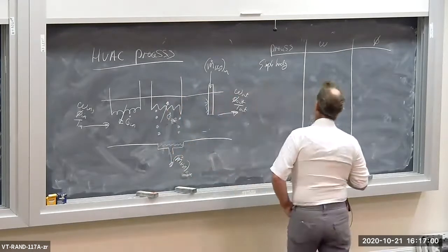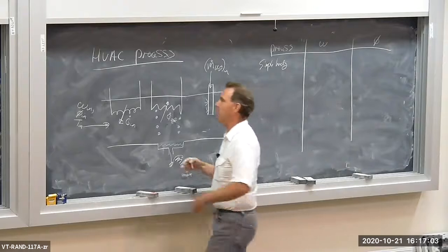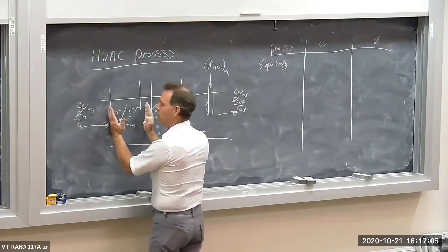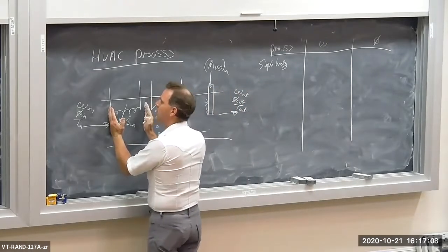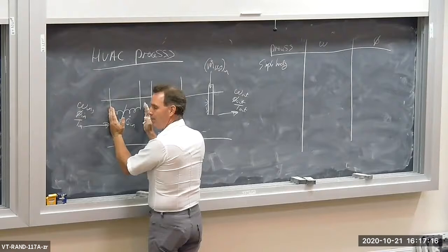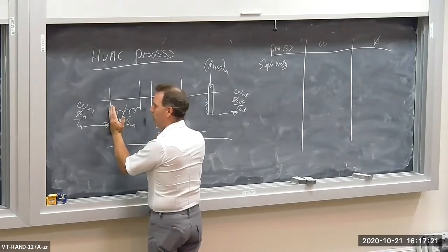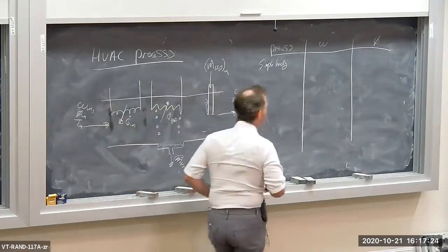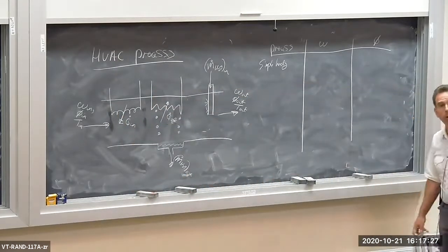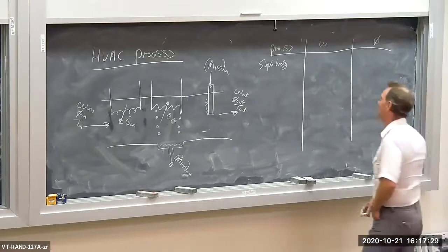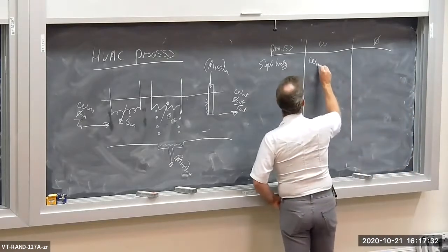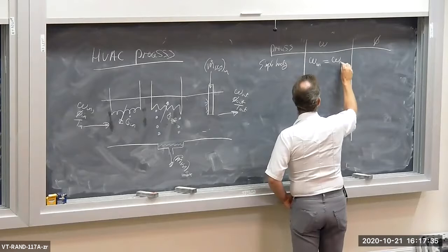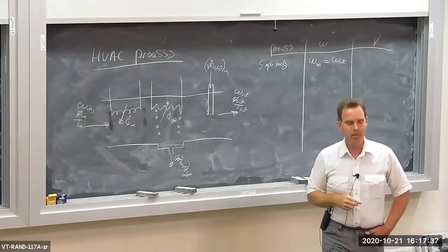So in that case, if you do a mass balance on the dry air and the H2O for simple heating, no humidification, no dehumidification, no water being added, no water being extracted, you get m dot dry air in is equal to m dot dry air out, m dot H2O in is equal to m dot H2O out, and therefore the absolute humidity or humidity ratio at the inlet is equal to that at the outlet. So we'll get omega in is equal to omega out.